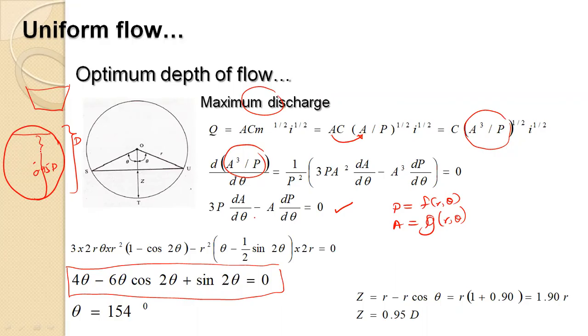Sometimes you need to have certain velocities. We study about the maximum velocities in the channels. Generally, there is something called a cleansing velocity. If there is a debris or some material and you want the material to flow along that channel, we want to make sure that it has sufficient velocity along the pipeline.